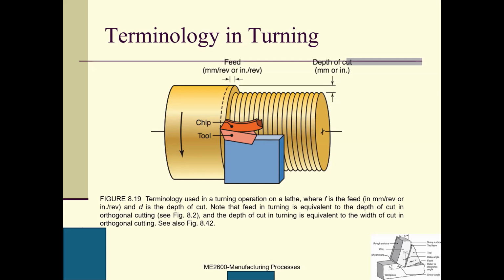Just a question: what would it be classified as if the tool is bigger than the workpiece? The width of the tool is supposed to be bigger than the thickness of this wall. Otherwise, you will have a shoulder, which means some material your tool cannot cut.